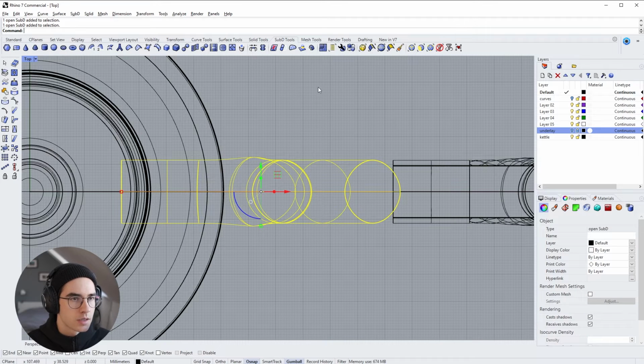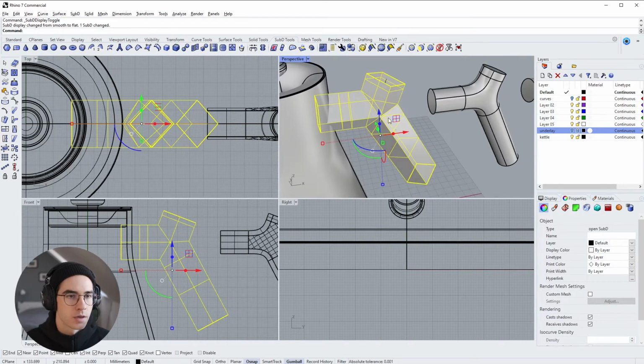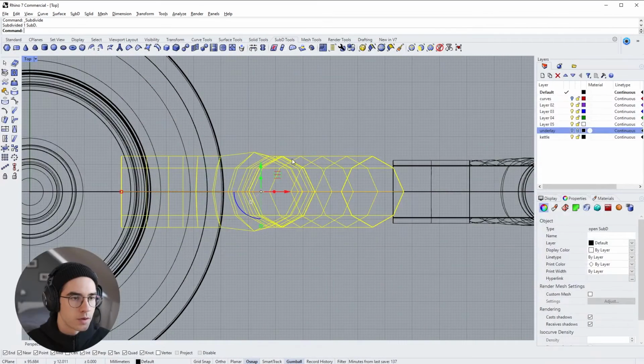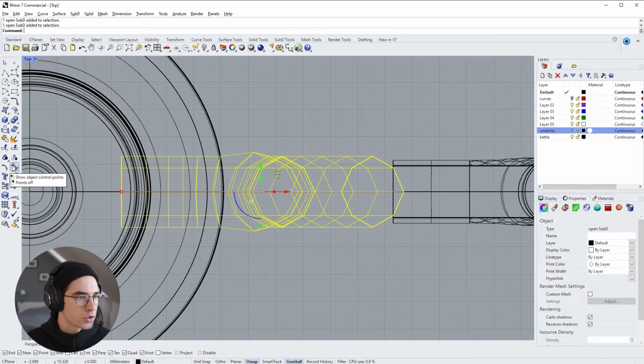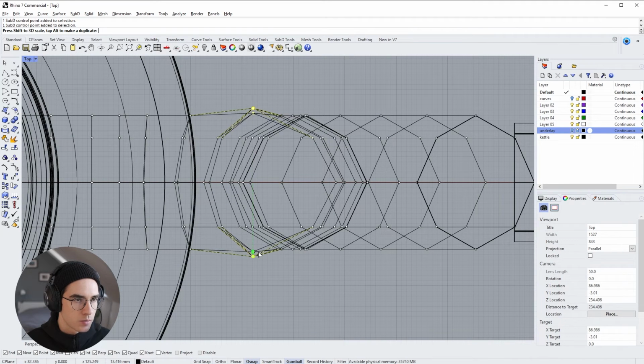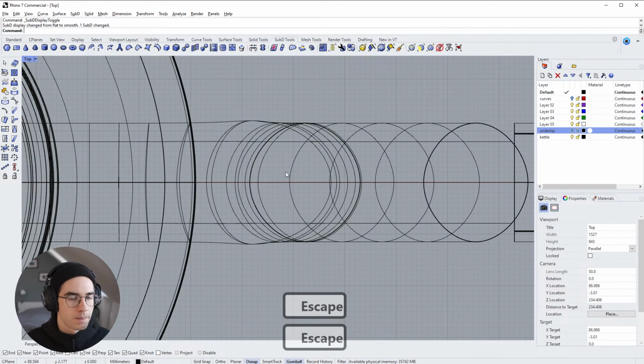In order to do this, we can select it, toggle subdivision display. You can see that the actual model that it subdivides is made of basically quad shapes. And in order to tweak it a little bit, I want to subdivide this model. So hit subdivide subdivision. Here you can see from the top that the bulge is now visible. If we now go to standard and show control points, we can just take those two rogue points and move them inwards. So it will not delete the bulge entirely. If we toggle subdivision again, you can see the bulge is much smaller, and it's not as apparent.